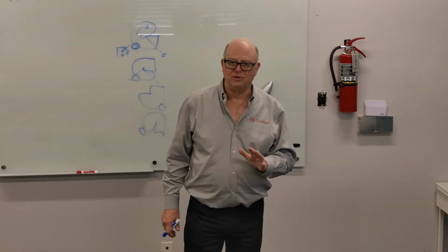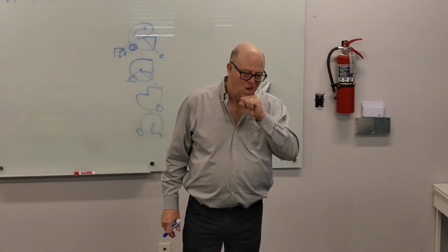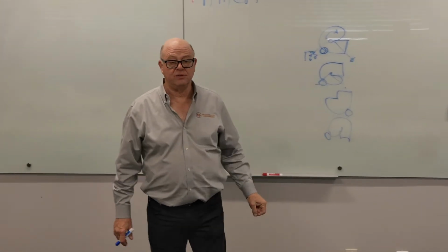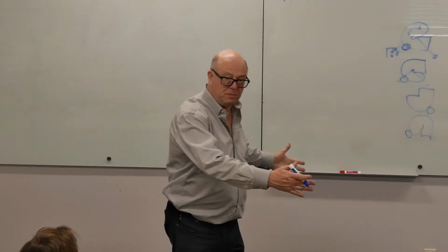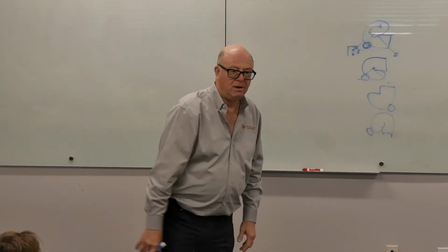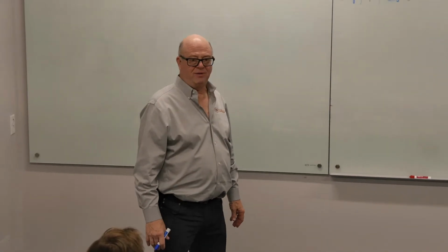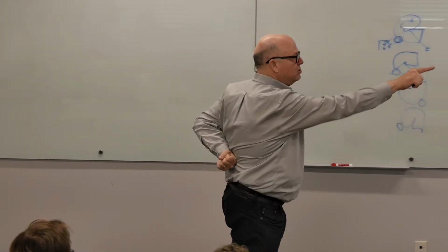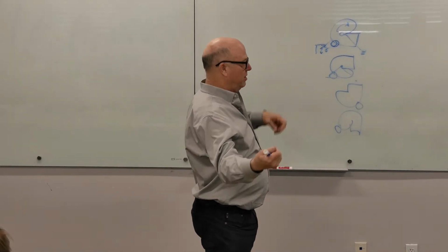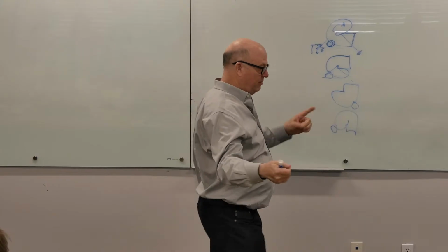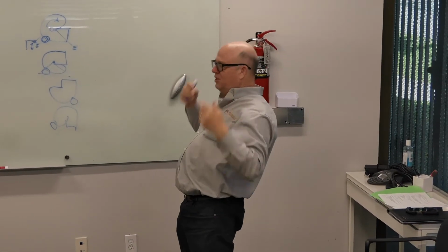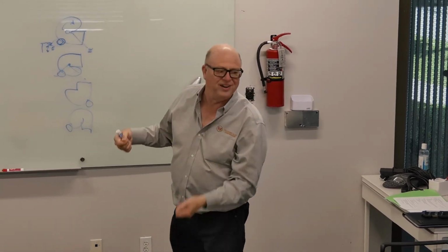There is no consistency in the world. And I'll give you one example, but the same is true for just loose fans like this. An air handling unit, which of course we talked about last week, is a cabinet fan. If it's a Carrier cabinet fan or a York cabinet fan, you're looking at the back end, the air's hitting you in the back, air's going this way, and that defines right or left hand. If it's Trane or McQuay, you would stand in front of it with the air blowing in your face, and that would define which is right or left.